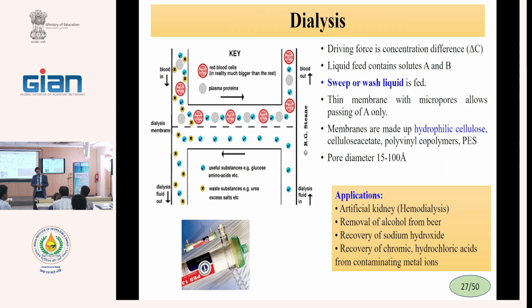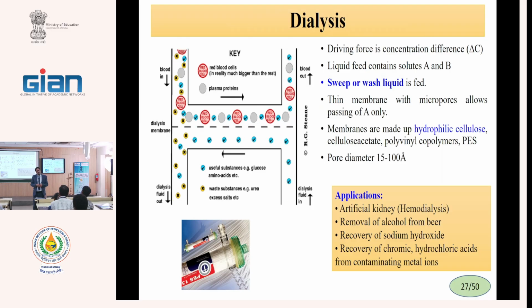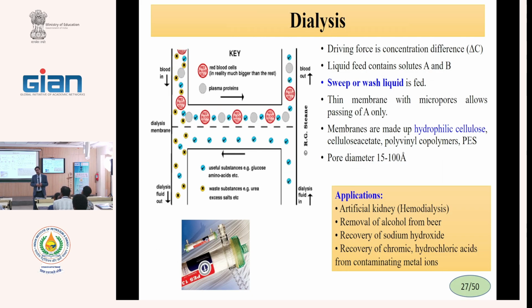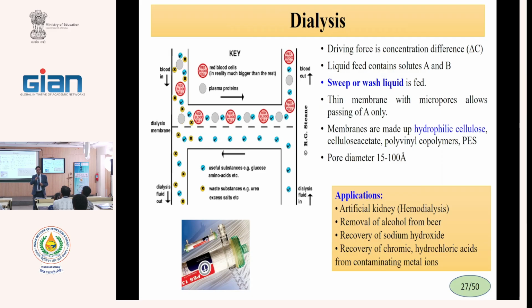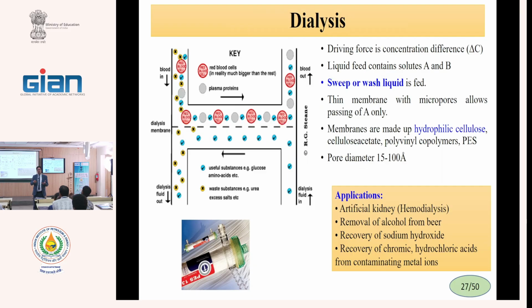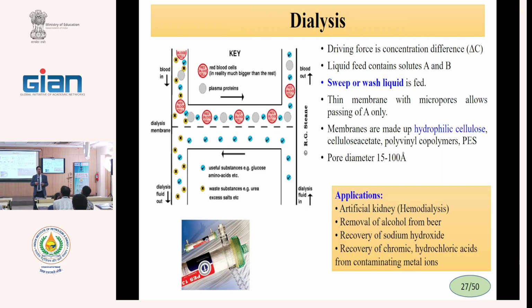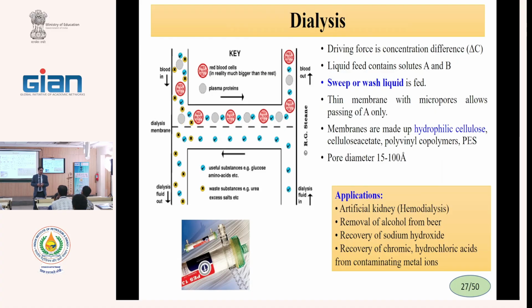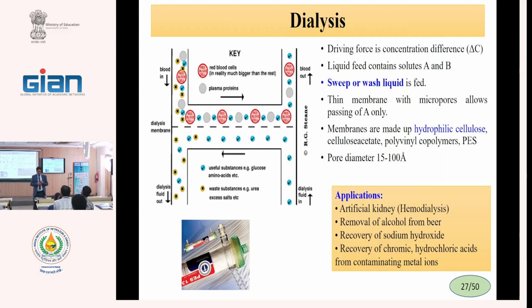And also we face the problem of DMF and water. We can't separate that because it will form an azeotrope at 100 degrees Celsius itself, where water has to evaporate. So we can't do it through a normal distillation process. Is that possible with your membrane technology, the DMF separation? You want to remove DMF or water? We want to separate DMF itself because of its high temperature. How much DMF? Generally, I encounter 5% DMF and 95% water. In lab scale? Yes.